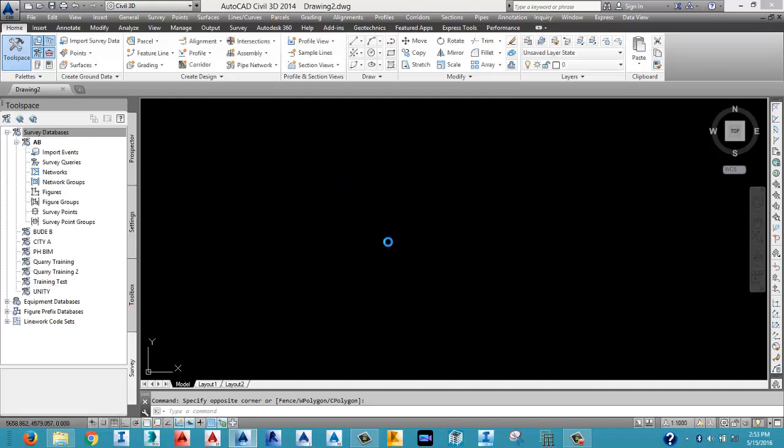Once I click on OK, I give the software some seconds, not even up to a minute, to generate that database. After clicking on that, you can see on my left hand side I have my AB database being generated, but there is no information in this database yet. So all I have to do is bring in my survey data, as I've shown you outside, into this database, so that I can have it saved here and call it up anytime I need to make use of it. So you go to your import event, then you click on import survey data.